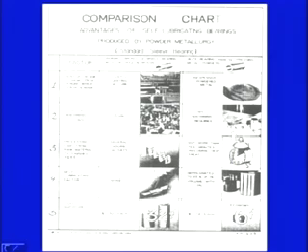In the powder metallurgy route, inexpensive powdered metal is used. The cost of machining is usual, whereas here no machining is required. Processing time is several hours or days for the ordinary bearing, while in powder metallurgy it is not more than 10 minutes including heat treatment. Moreover, the self lubricating factor is not there in the ordinary bearing, whereas in powder metallurgy the self lubricating characteristics are present in the part. The cost is also comparatively more for the ordinary bearing.